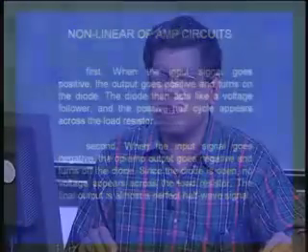Okay. Once we can get an ideal half wave rectifier, the question then is how to build a full wave rectifier. We always require a full wave rectifier when we want to amplify a very small AC signal. When you want to convert it to DC, it will be nice to have a full wave rectifier. In the case of a normal full wave rectifier, you will use a transformer with a center tap, so that with reference to the center tap, the two ends of the transformer will be out of phase by 180 degrees, and therefore I can use 2 diodes to convert each half of the cycle, and get a full wave rectified signal.